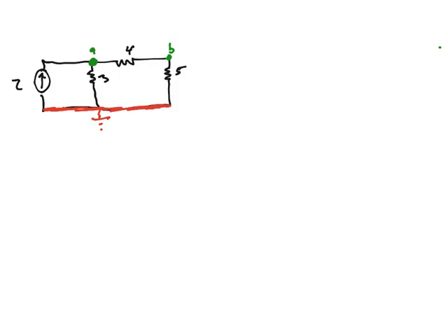All right, so I've chosen my nodes. I've got my ground. Last step before I start writing equations is what are the currents? So I'll do that in yellow. Okay, well, for node A, I have I1 coming this way. I2, I'll choose to be going down this way, and I3 will leave to the right.